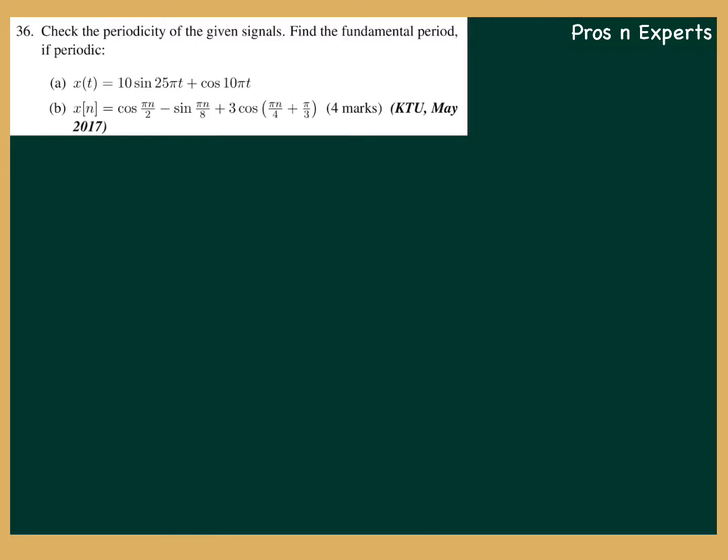Okay, welcome to the next question. Check the periodicity of the given signals. Find the fundamental period, obviously if periodic. First question, x of t is equal to 10 sine 25 pi t plus cos 10 pi t.